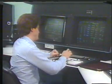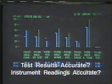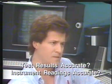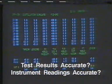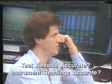You should always be skeptical about tests and instruments. A situation that seems abnormal may only appear so because of faulty instruments or test results. Double-check instrument readings and test results before making changes in tower operations.